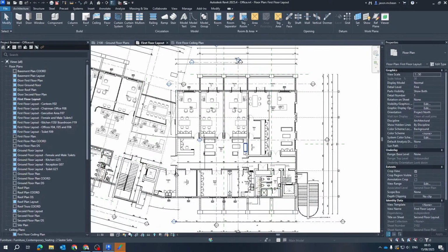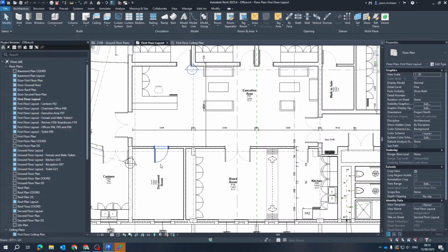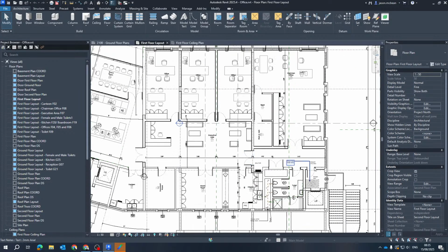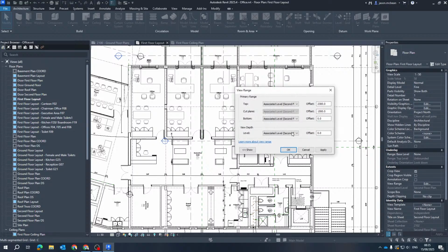Now this is quite tricky to understand. You'll see, now these ceiling layouts depend on quite a few things. You'll see on the ground floor plan that all our door openings are showing. A lot of the brickwork will go up to the underside of the slab if you're going to compartmentalize your building for fire. So some walls will need to go up to the underside of the ceiling so you form a fire barrier between compartments in essence.